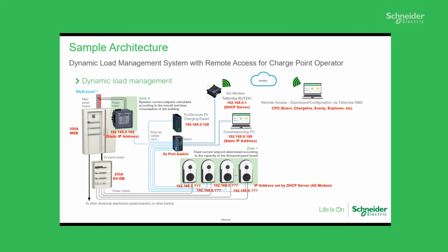EcoStruxure EV Charging Expert comes with a default IP address of 192.168.0.128. Therefore, I have decided to maintain this subnet across all other devices on the network. Subnet mask will be 255.255.255.0.